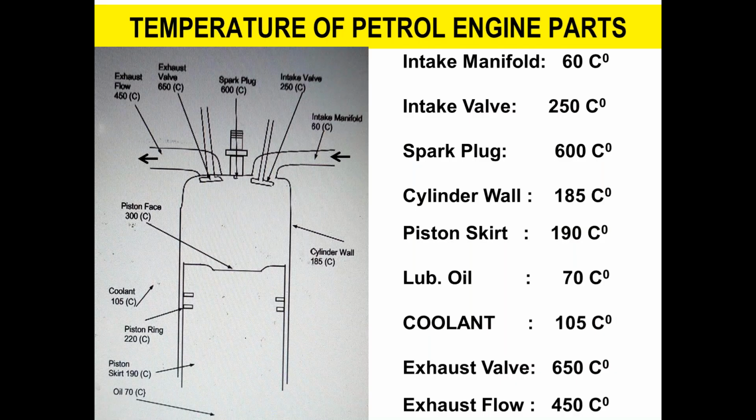See the temperature of petrol engine parts. Here you see the piston, this is the cylinder, and then the intake manifold is at 60 degrees centigrade. Here is the intake which sucks air from here. Then the intake valve is here at 250 degrees Celsius. Then the spark plug is at 600 degrees Celsius.